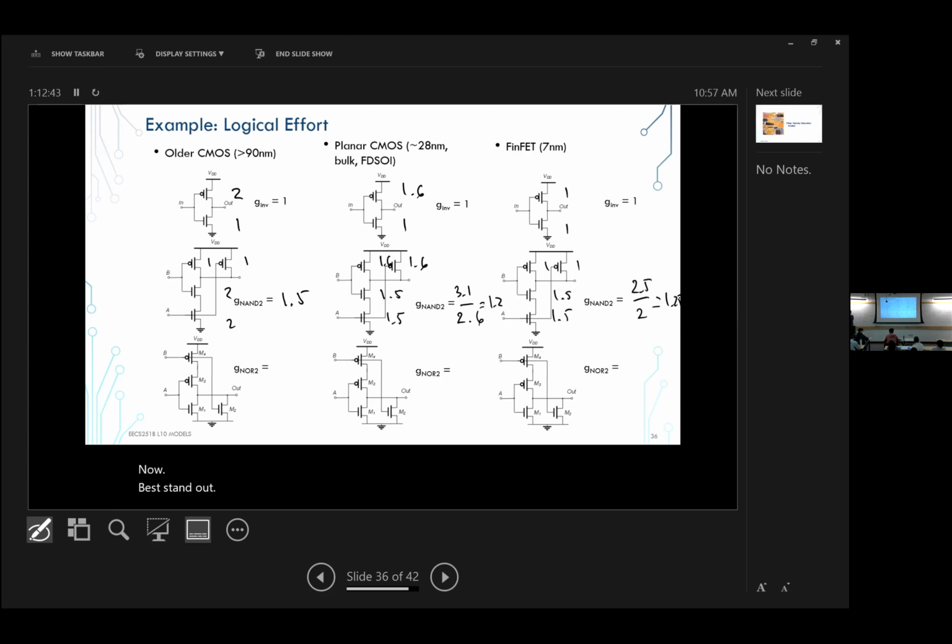Yeah, somewhat. Essentially, NANDs or stacked devices became better drivers. That was very favorable, right? We could build more logic in the same number of stages. Some people predicted the end of scaling. There is a paper that was well cited in the 80s from a really well-known faculty at that time at a university across the bay that says scaling is going to end because of velocity saturation.